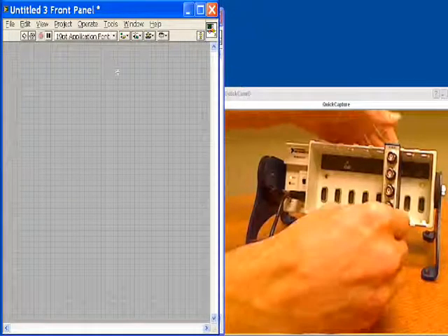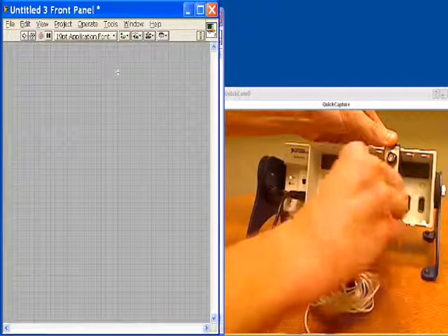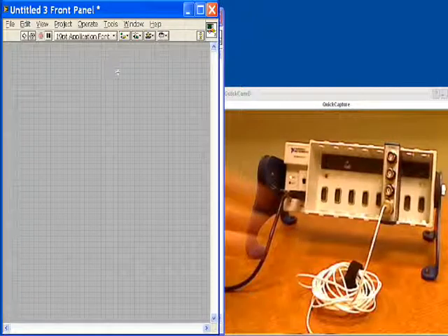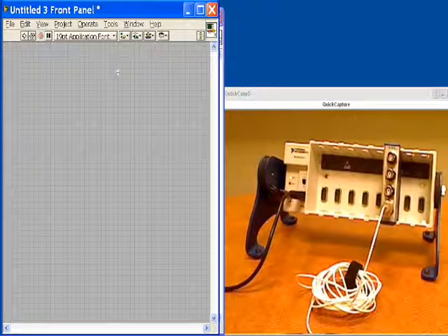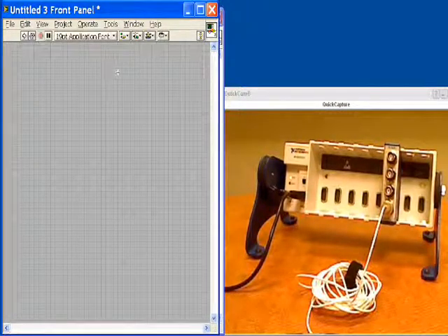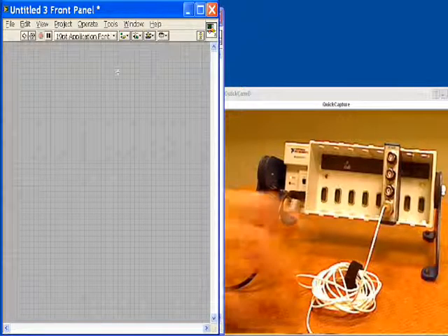And then for the accelerometer, we have a BNC connector, as is common for accelerometers. I'm going to go ahead and plug that into channel 3 of the system. And now from a hardware standpoint, we are all set up. So let's move over and look into working with LabVIEW.